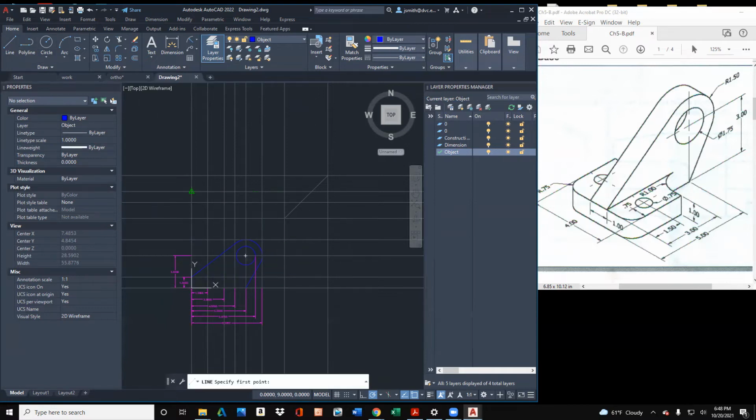So the center is coming here, here, like this. So I'm just drawing on my construction line. I don't really have to think too much about it. I've got a couple radiuses here that I need to deal with. So let's just, I can do a little radius here. I've also got the circle that's in 0.75. Let's go ahead and build that construction line. All right, so more construction lines. So that you'll see the advantage of this in a moment here.